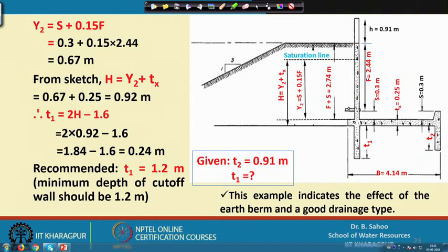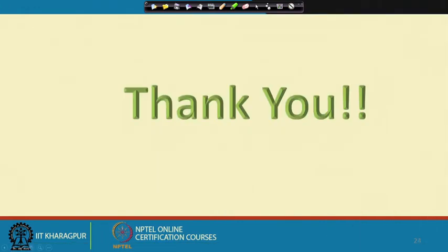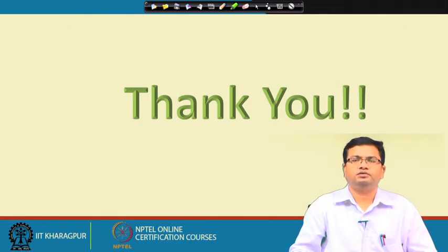From this lecture we summarized what the contact pressures are, what piping failure is, what the main causes of piping failure are, and to withstand piping failure how we will design our depth of cut-off wall, and what the optimized depth of cut-off wall is. We also discussed overturning depending on the uplift pressure and the vertical pressure loads, at what is my z, or the eccentricity, according to that whether it will be overturning or not.